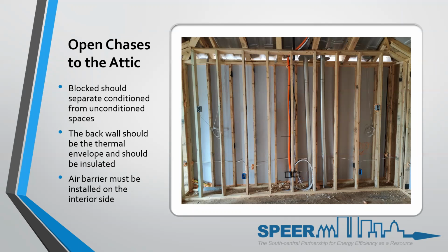They should probably have angled those flue pipes up and away as quick as they could out of the house and go up to the right. But instead, they just go all the way up to the roof line. Not anything of energy that you can call out to say, hey, you need to move those flue pipes. It's just, now I have to make sure that it's air sealed at the top and it's capped at the top and it's insulated where the thermal boundary meets the outside envelope and it's done correctly.